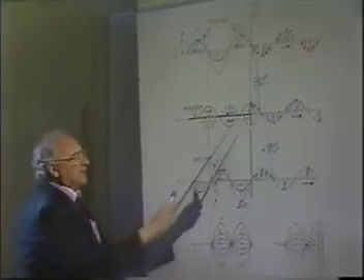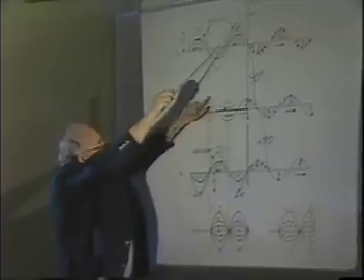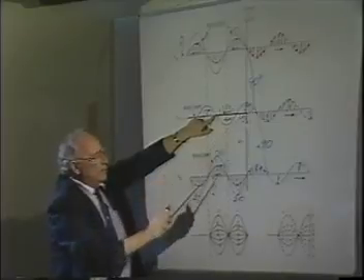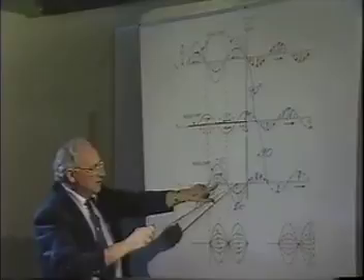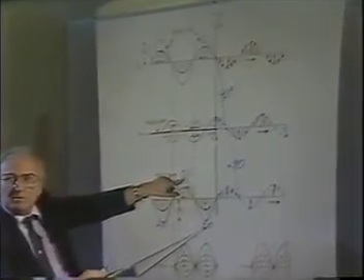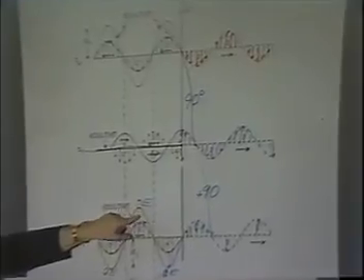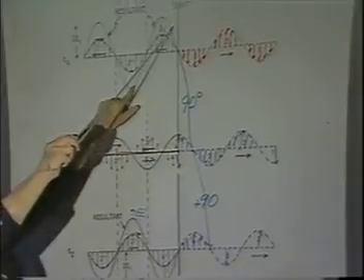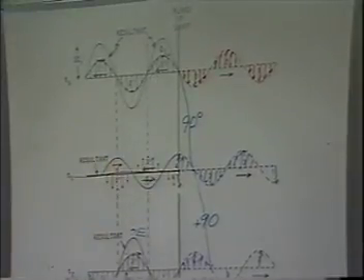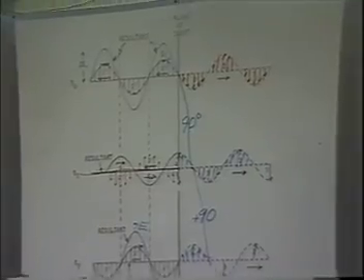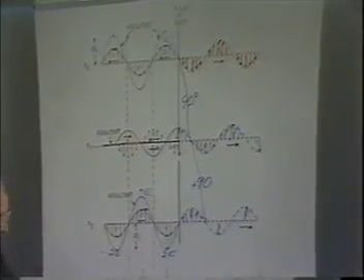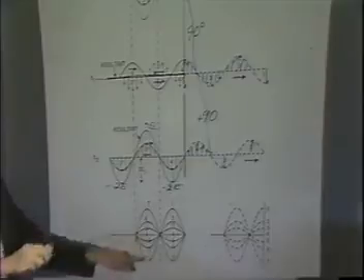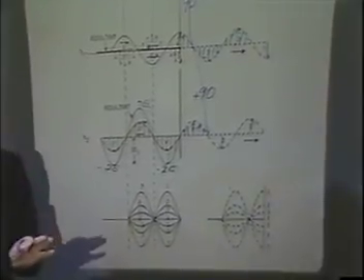When the wave travels to the right, then 90 degrees, this collapses from here all the way back to 0. So now you have 0 voltage at all points on the transmission line. When it travels to the right another 90 degrees, then it goes from 0 to this point. Okay? Then the next 90 degrees, it goes back to 0. The next 90 degrees, it goes back to this position here. So when the wave travels to the right 360 degrees, this waveform goes 90, 180, 270, 360. And it just keeps doing that, standing there. A standing wave of voltage.